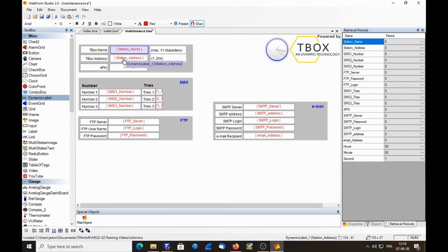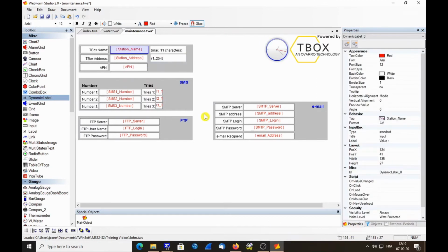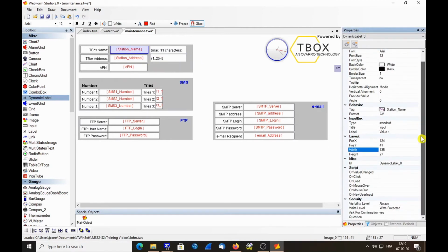Remember that the object here, the runtime parameters here, you want to change them. So make sure that you have given a right level, which in our case must be a right level engineer, because remember, only an engineer can change the value. Ask confirmation, no. So you have to do that for each object. Right level engineer, access protection, no.